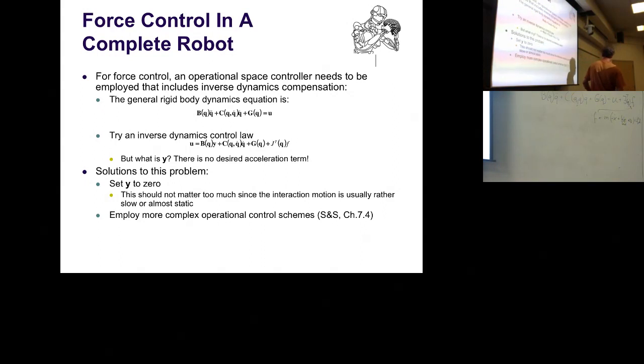Okay, so actually it's very simple now. From our simple 1D mass system which we analyzed, we can plug it into a nonlinear system and still do our control as before. So we actually have a reasonably useful force controller. Forget about the y, as I mentioned. Just drop this term, and it's going to work okay. It can do better, but it will work nicely.